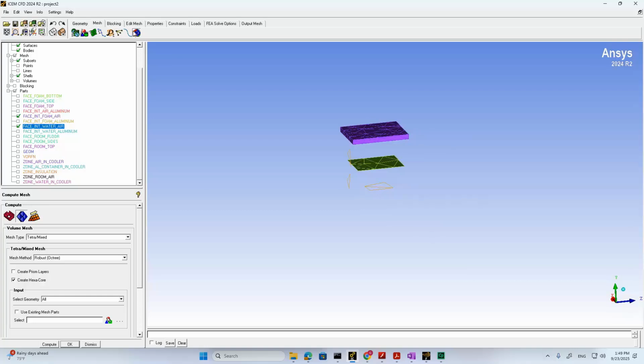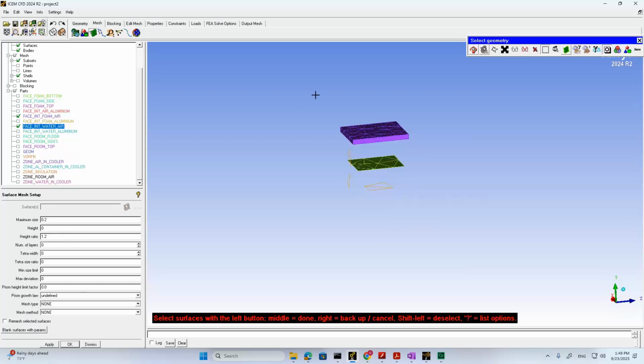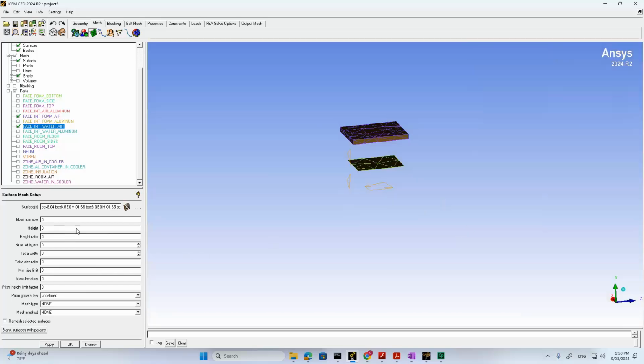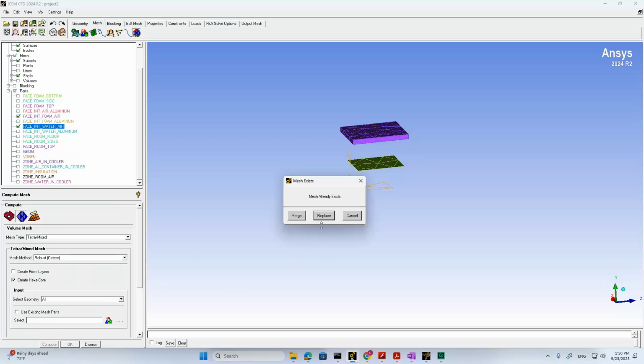Right. So then I select all these surfaces, and now I want to use like 0.1 for example, and the ratio is 1.15. The smaller this number is, the better the transition between different mesh densities you have, but definitely it has to be greater than 1. It cannot be 1. It has to be at least like 1.01. Then we redo the mesh.